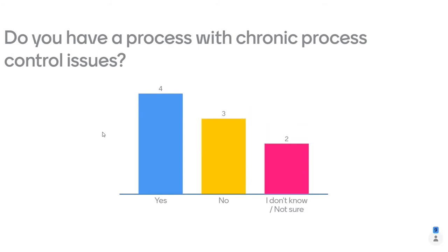So yeah, it's one of those situations where when we talk with engineering, when we talk with operators, there's a heavy reliance on basic process control system, BPCS. And sometimes, and at least in our estimation, sometimes there's an over-reliance on these things. Sometimes people feel if there's an interlock on a valve, that it'll never fail, and that is our safeguard. That's our gold standard, an interlock in a valve. But if you look at the various PFDs for various interlocks, you'll find that they do fail, and they fail probably at a higher frequency than most people would think. And so it's something you want to think about.